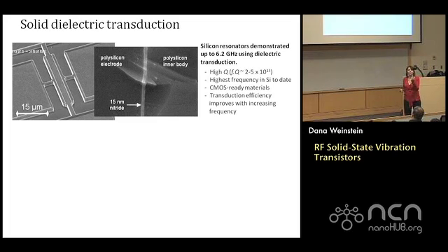This film is squeezing, expanding and contracting as this thing is vibrating. But we have to have that capacitor built into the resonator itself. So what you see here is a silicon bar resonator. It's expanding and contracting in this direction, in the plane of the wafer, so that I can lithographically define different frequencies on a single chip, which we want to be able to do. Almost everything here you see is silicon, except for these two bright lines, which are actually sandwiched dielectrics inside this resonator.